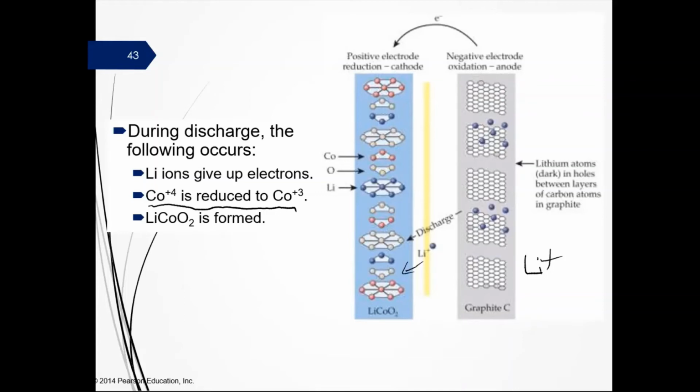And then when we're ready, when we recharge our lithium-ion battery, we slowly convert that lithium plus back into lithium solid. And so those lithium will migrate back into that graphite where they become lithium metal, and they'll be ready for our next discharge. So over time, we kind of have this rocking chair impact of our lithium going in one direction when it is releasing energy, going in another when it is gaining energy. And that's how we can make our battery work.